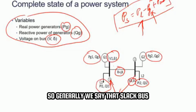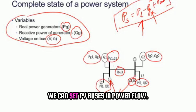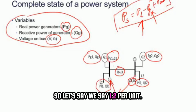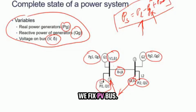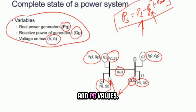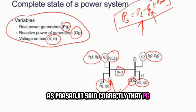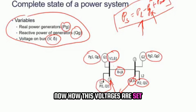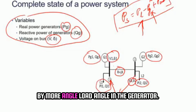Generally we say that the slack bus generator is kept at 1.05 or any value. For PV buses in power flow, I'm talking in terms of per unit, so let's say 1.02 per unit or 1.01 per unit. We always fix, for all the generators except one, the PV bus: we set the voltage and the PG values. And PG values, as Prasenjit said correctly, are set from economic dispatch. I completely agree. Now, how are these voltages set? By power angle, load angle in the generator.